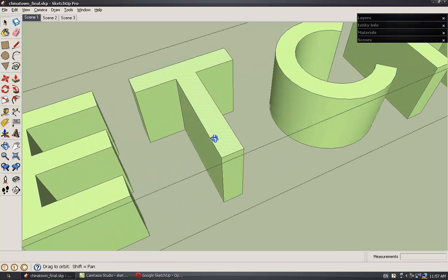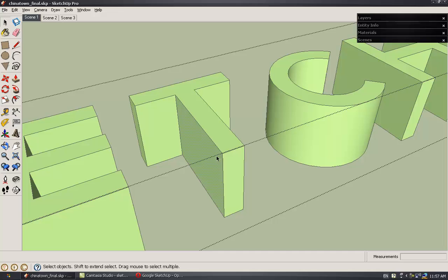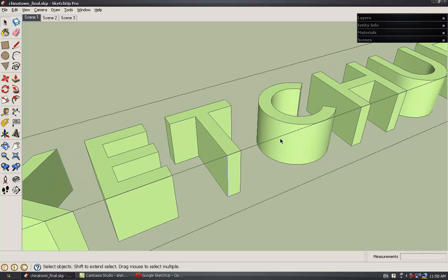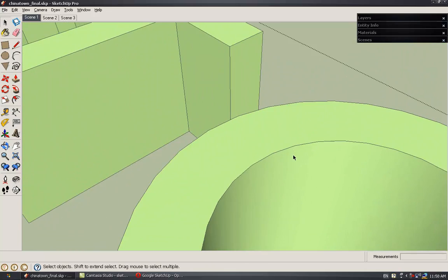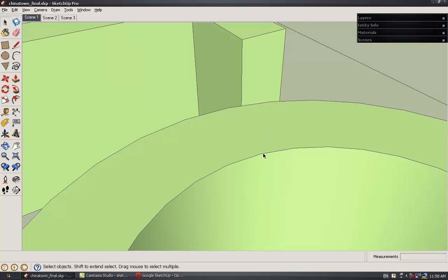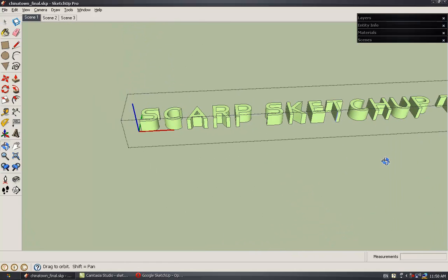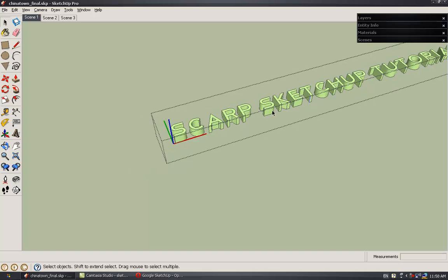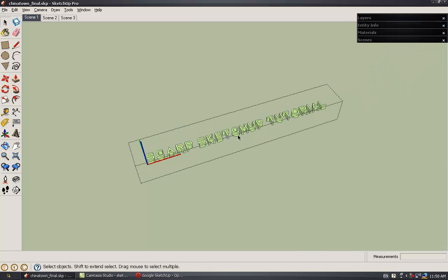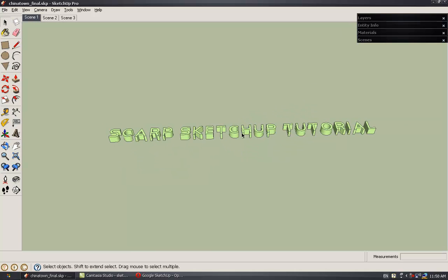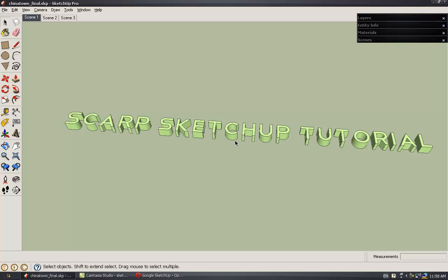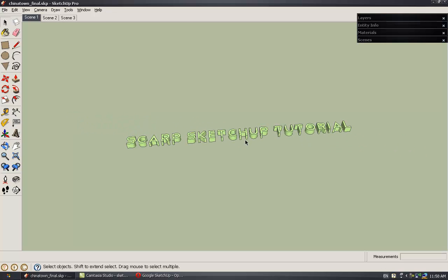So as you can see, these shapes are made up of polygons surrounded by lines, which are then anchored by points. And if you look at the curves here, they are in fact straight line segments. It's not a perfect curve. So SketchUp is excellent for massing models, large building models. It's not great for organic modeling or overly precise product design, but for mocking up things and especially for building quick neighborhood models, it is an absolutely invaluable source.